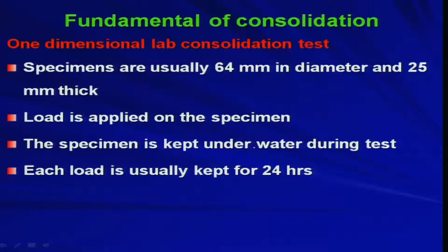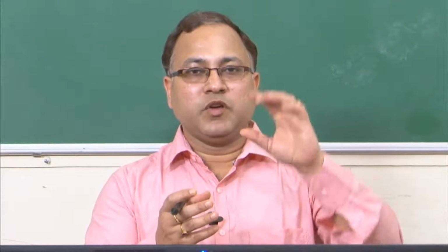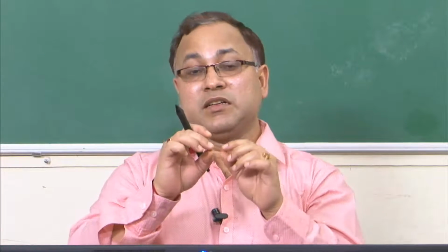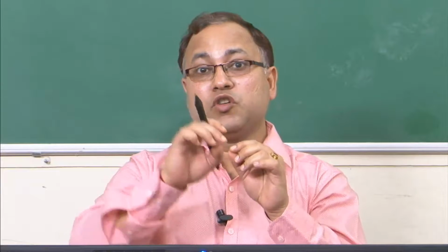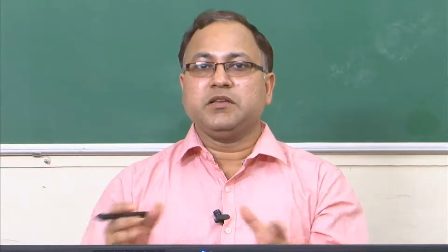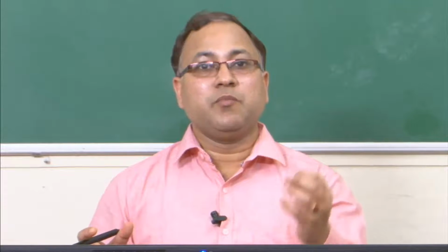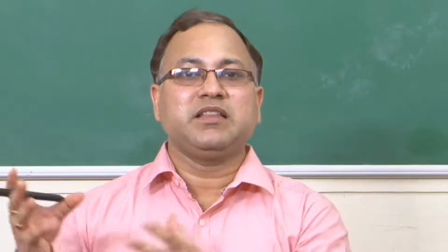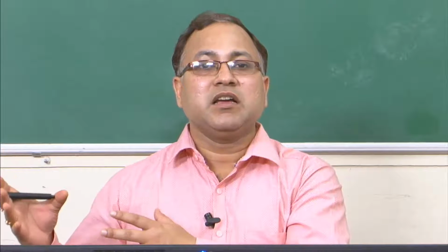Each load is usually kept for 24 hours. So, this is a pretty time consuming experiment. So, you apply the first load and you wait for 24 hours to deform, because you have to consider t equal to 0 to t equal to infinity, right. So, infinity is so called almost 24 hours. So, after that you will be getting complete dissipation of say pore water pressure, and whatever enhancement you will be getting, that will be happening in the effective stress, right.